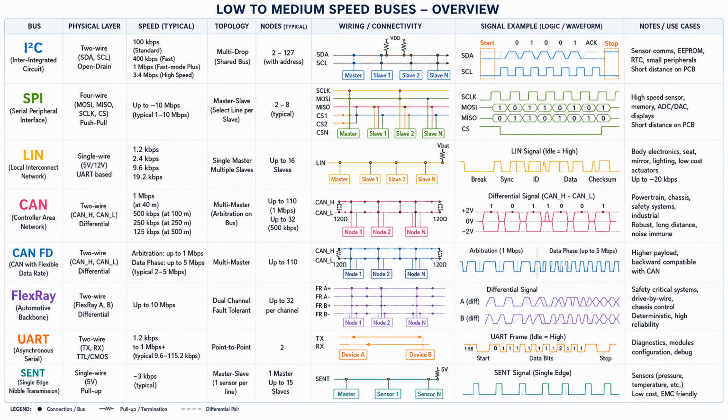Section 7 talks about UART, Universal Asynchronous Receiver Transmitter. UART is one of the oldest and simplest serial communication methods. It uses TX and RX. No shared clock exists between devices. Instead, both ends agree on a baud rate.